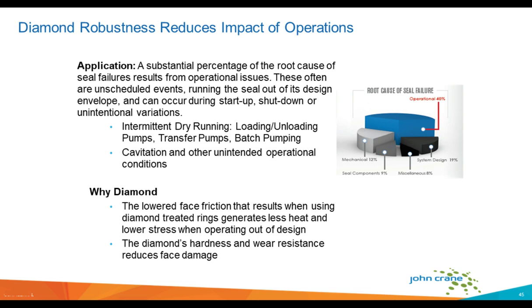When we look at a cross-section of typical mechanical seal face failures, the lubrication-related damage is inherently involved in one form or another in the greater percentage of seal failures. So again, the diamond treatment helps the seal faces survive these intermittent dry running events.